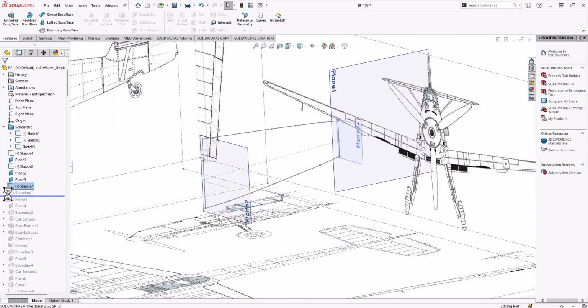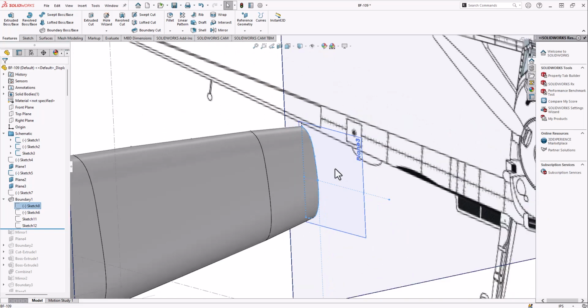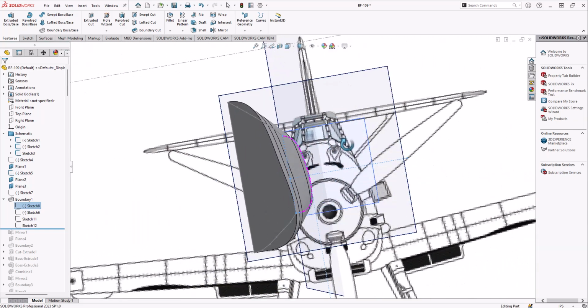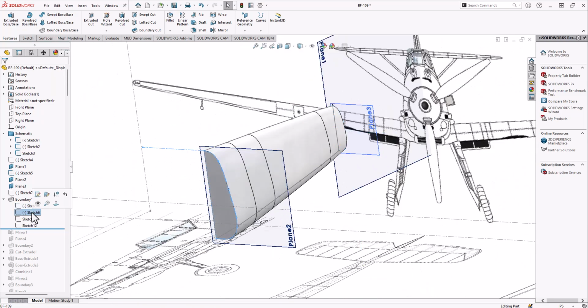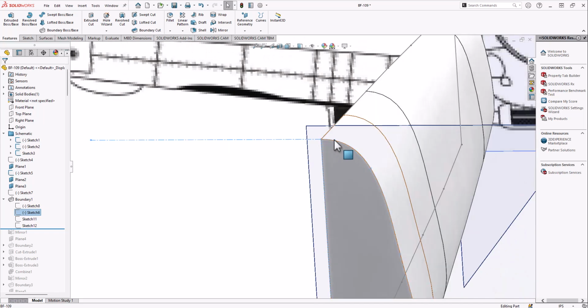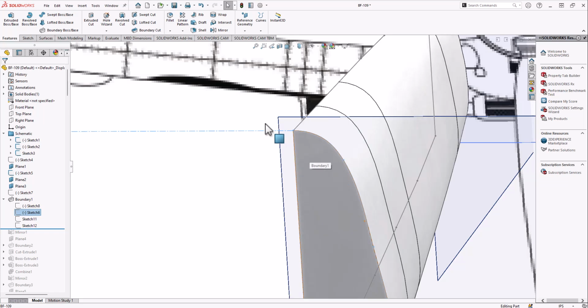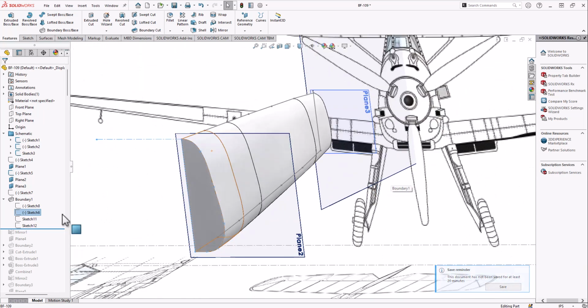So I'm going to skip that, but what I can do, this is going to jump a step, is I create a sketch on the front here, or on the back here, that has the contour that I want the back of the aircraft to have. Then I have the front contour, and I use this line and a tangency constraint on a spline here to have it come perpendicular, at a right angle at the top here, so when I mirror it, it will smoothly transition.